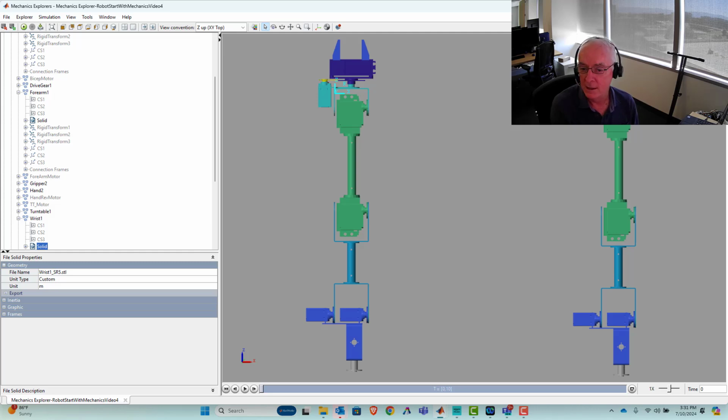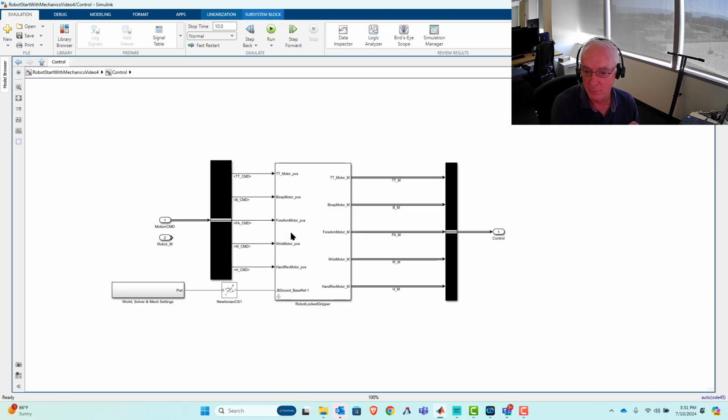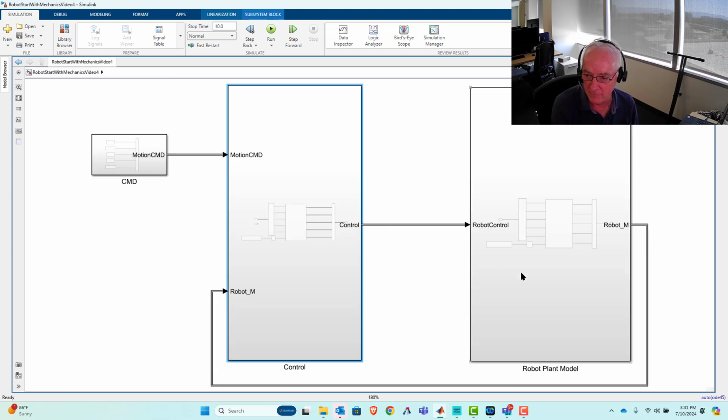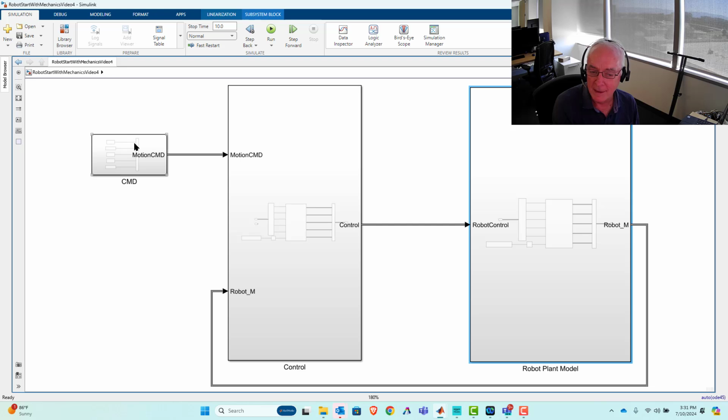Even the smallest of errors matters. What we're really doing is using an identical mechanical model in our controller, meaning all the masses, geometry, inertia, all that kind of stuff is exactly the same as what we're representing the real robot with in our plant model. It's all the same, and it means that on this computer the numerical error of calculation, probably on the order of 10 to the minus 16th, is enough to trigger an instability. In other words, 1e-16 becomes very big very rapidly.